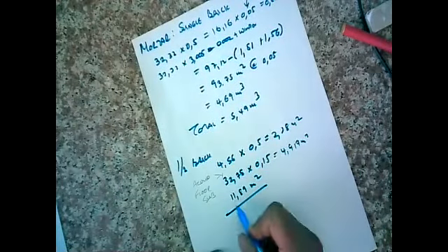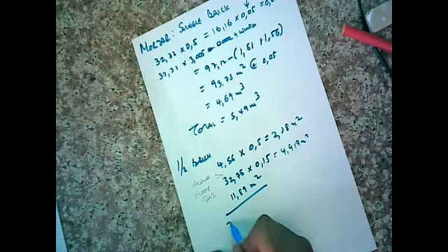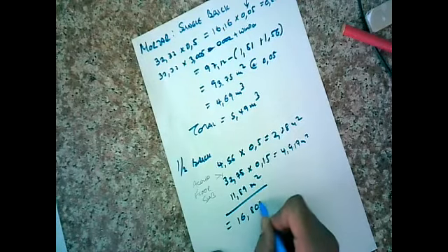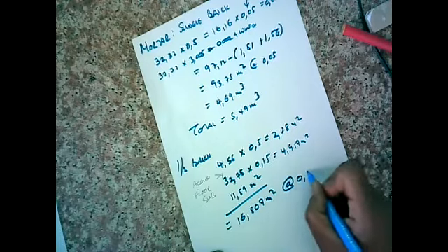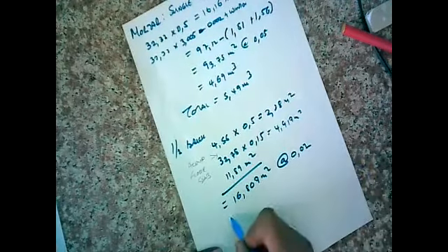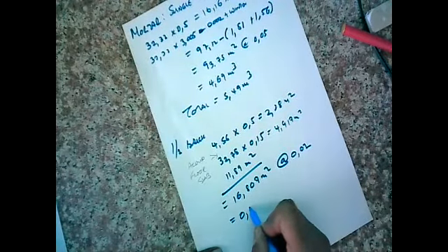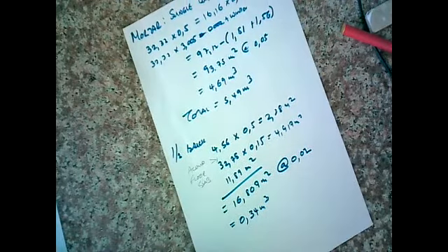Notice we've got 3 of them. Getting a total there of 16.807 meters squared. Now, half brick is a different volume per meter squared, and that's 0.02. Check that table out to confirm, and we're getting a value of 3.4 meter cube of mortar.